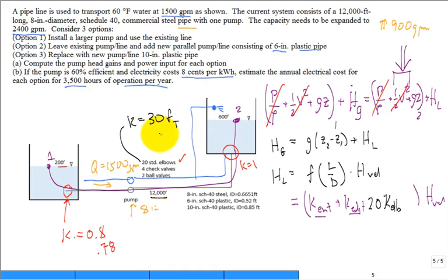I understand 30. What's F of T? The friction factor, fully turbulent for that diameter pipe. And that friction factor, fully turbulent for that diameter pipe, there's a neat little table, figure 1-7, which gives it. If you're running an 8-inch pipe, it's 0.014. So you're going to be different using that technique versus just grabbing the loss coefficient of, what did I say it was, 0.75. Anyway, this friction for 8-inch pipe, 0.014.